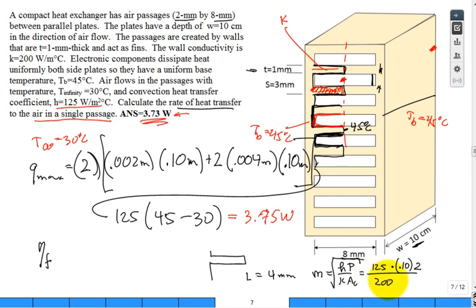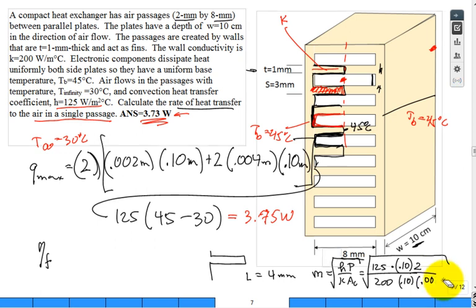What about the cross-sectional area for the conduction? That's going to be my W, 0.10. And then isn't that going to be my T? I can't neglect that. And what was that, 2 millimeter? 0.002. Okay, oh yeah, 0.001. You're absolutely right, 0.001.